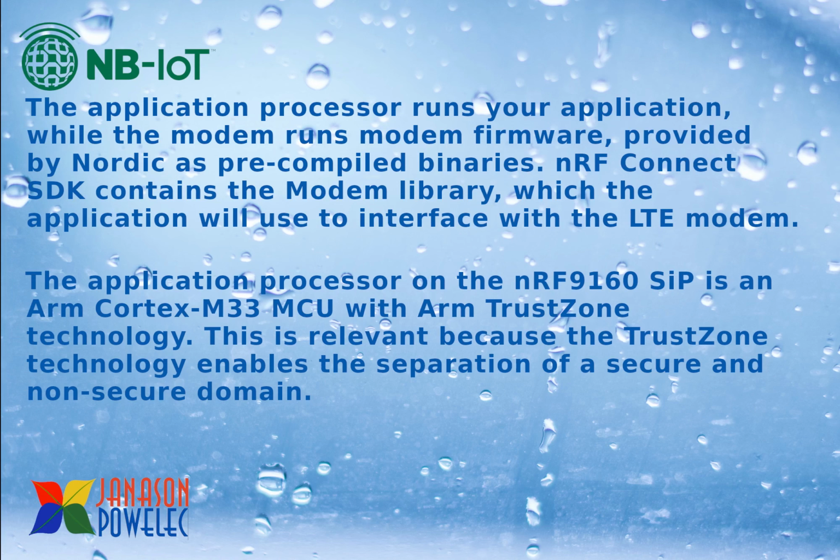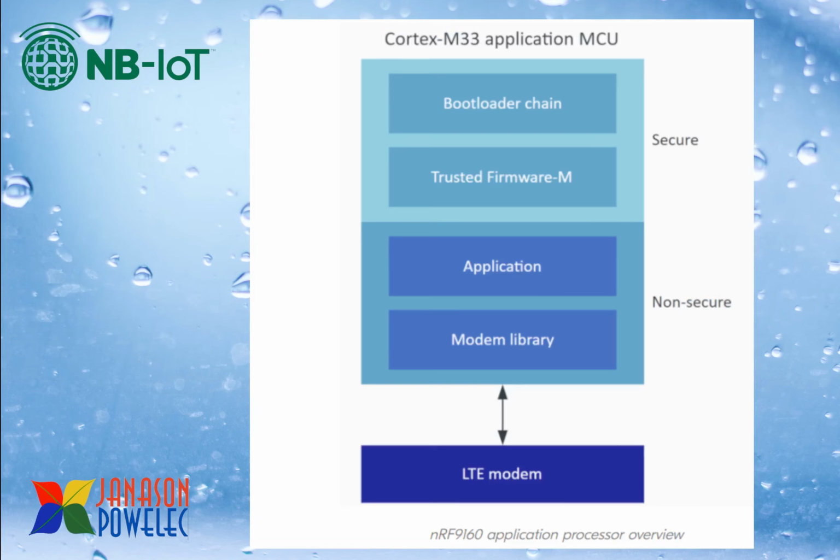The application processor on the nRF9160 SiP is an ARM Cortex-M33 MCU with ARM TrustZone technology. This is relevant because TrustZone technology enables the separation of a secure and non-secure domain. The Cortex-M33 application MCU has a bootloader chain, then trusted firmware. Both belong to the secure domain, and then the application area and modem library sit in the non-secure domain, and they connect to the LTE modem.